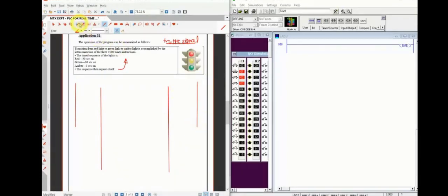Now students, in this case, most of the times, the input switches that we want are to start the signaling process, to stop the signaling process, or in some cases to reset the signaling process. So these are the three switches generally used in a traffic signal. So let us try to understand. It depends on you, students, whether you are using normally open or normally closed; accordingly you have to select the symbols inside this ladder diagram.